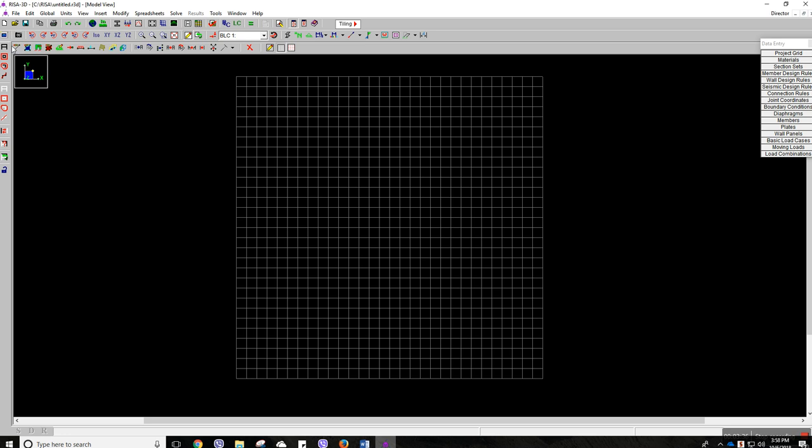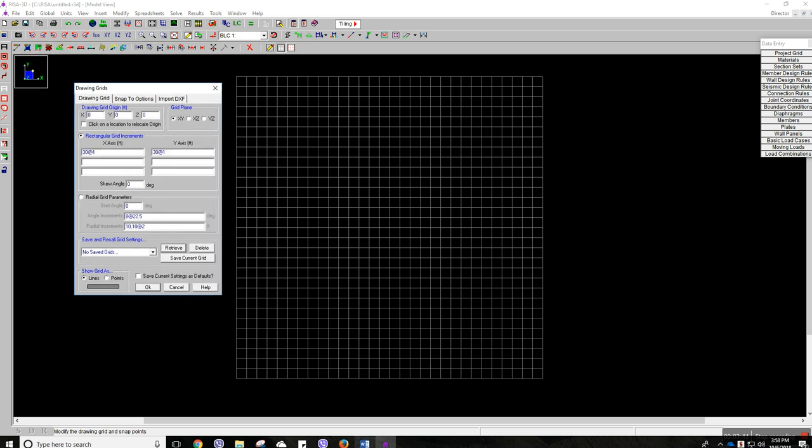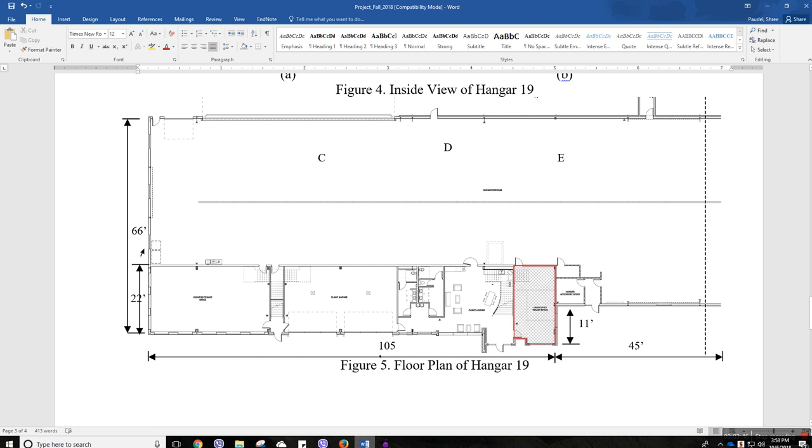Here you can see an icon with a pencil. It says modify the design grid, so click on that. I'm going to show you the structure again. You can do it any way, but the easiest method is this: this is going to be the front view, the height of the building, perpendicular to the paper, is going to be our y-axis, and the whole longitudinal axis is going to be the z-axis.